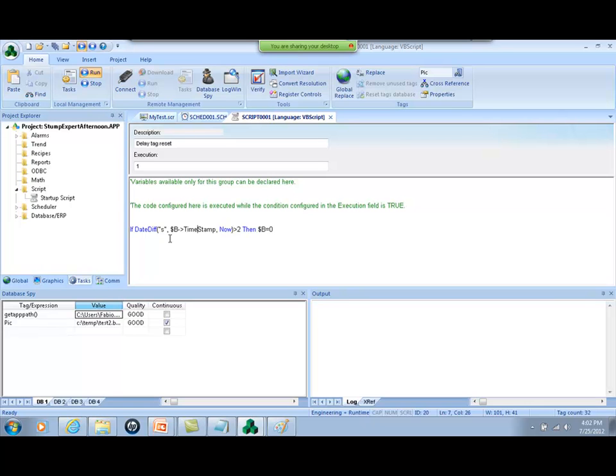There is just one caveat in this simple script here. The timestamp field from the tag B returns date and time in milliseconds, and the dateDiff function does not support milliseconds. So I can use here this function strGetElements on this timestamp, using dot as the delimiter and retrieving the first element to remove the dot milliseconds from the timestamp. And now it should work.